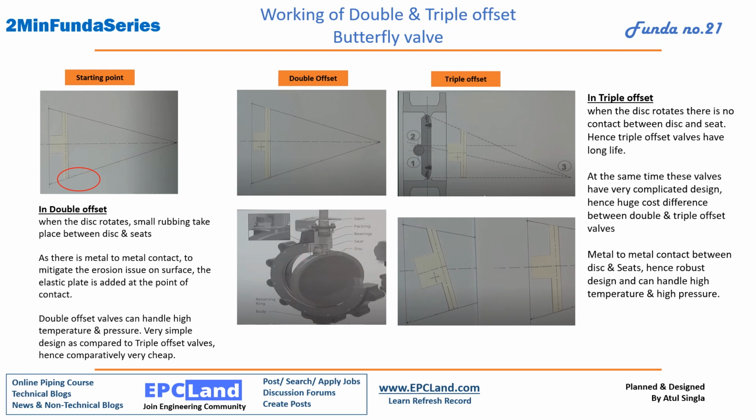The metal seat is there, the disc is also metal, so there is metal to metal contact. A small touch with the seat can damage it, which will be very costly to repair. So at the touching point we have an elastic plate. When the disc touches it, it will move a little, but it will avoid damage. Touching we cannot avoid, but a very small portion touches here as compared to before. We mitigate it by putting an elastic plate at this point.